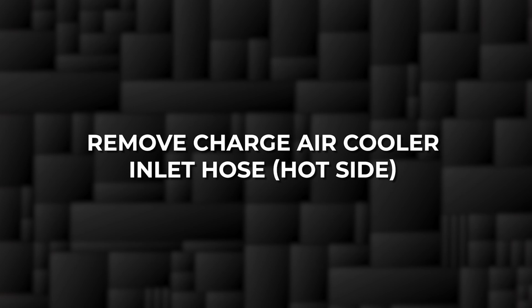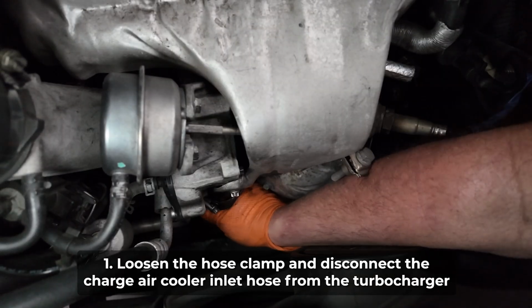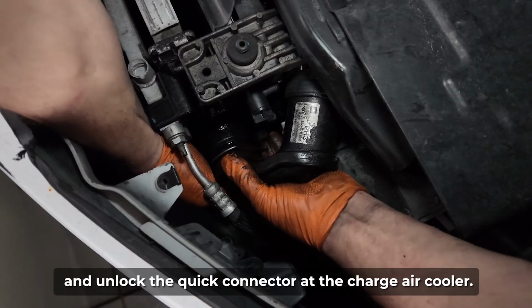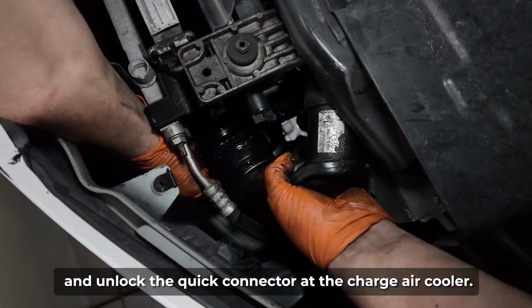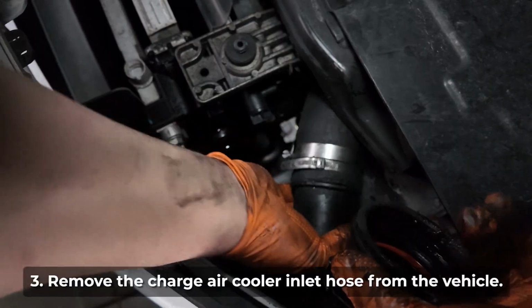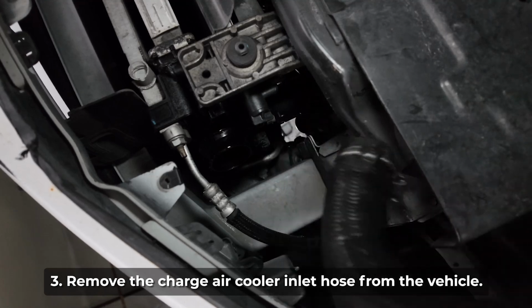We're going to remove the charge air cooler inlet hose. Loosen the hose clamp and disconnect the charge air cooler inlet hose from the turbocharger and unlock the quick connector at the charge air cooler. Raise the vehicle for access if necessary. Remove the charge air cooler inlet hose from the vehicle.